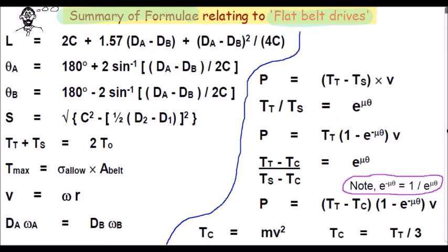So what are we trying to find? Well, we're trying to find the angle theta, the angle of lap effectively. And what are we given in the question? Well, we're given the friction coefficient, the damp environment. We're explicitly given the slack side tension of the rope, and we're implicitly given the tight side tension of the rope, the Tt here, because we're given the mass that has to be raised. We need to be careful with our units here.